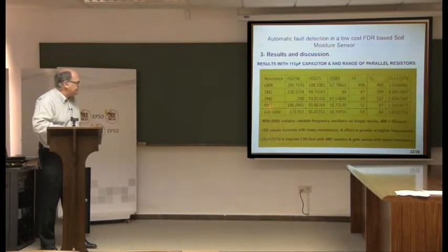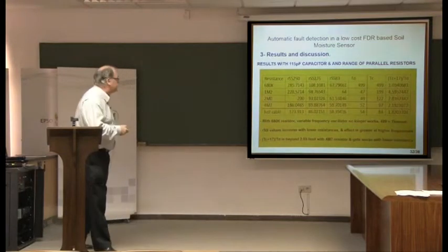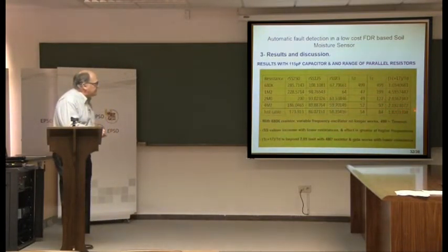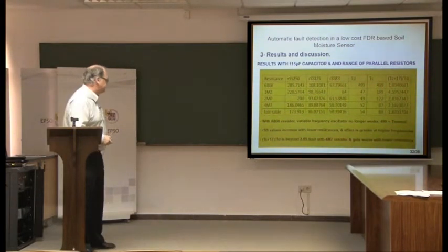But as soon as we put a resistor here of 4 meg 7, and as those of you will know that's quite a large value of resistance, our values have strayed outside that magical range. This is greater than 2.05, and indeed as we made the resistor smaller and smaller and smaller, that value got larger and larger until we got to a point where the oscillator would no longer oscillate. These 499 values are a timeout value. I mean, the circuit was not oscillating.